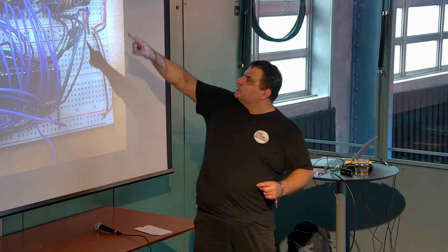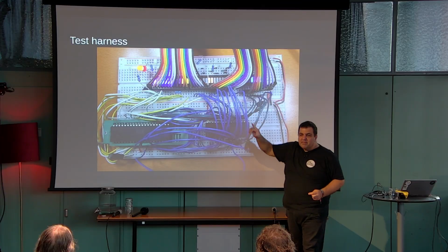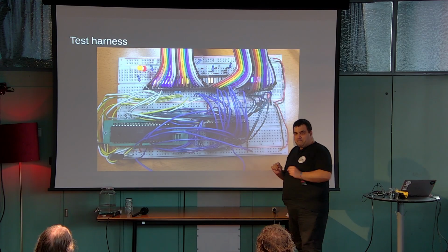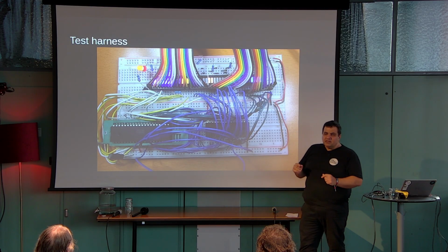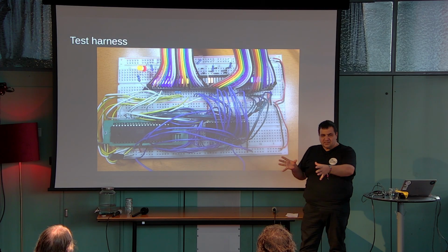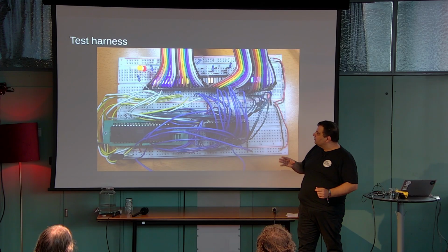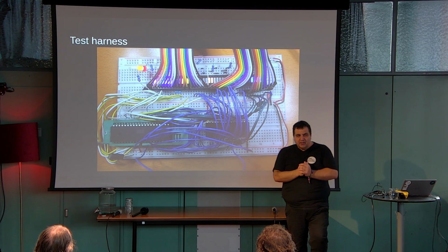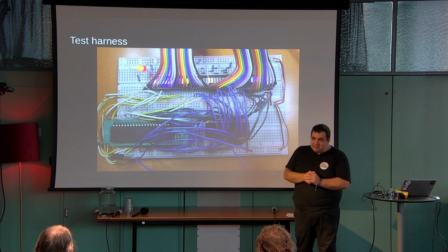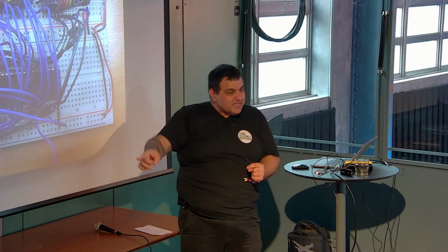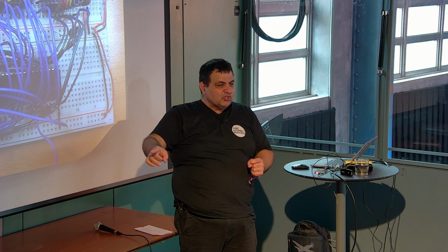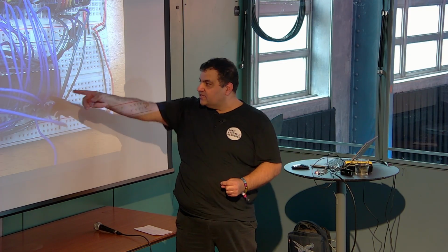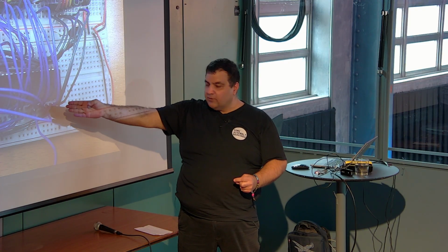So you see all of those lines going out. They're connected to an Arduino Mega, which essentially can look at the entire bus and control pins. So the clock comes from the Arduino. And then the Arduino is connected to a PC, which can take the program, because this doesn't have any ROM. So memory is volatile.